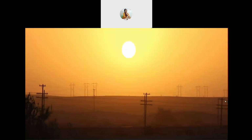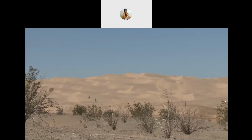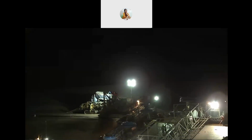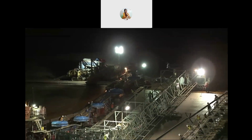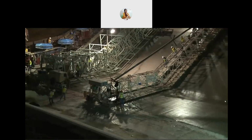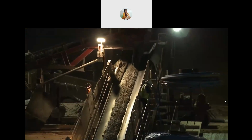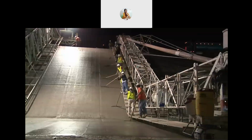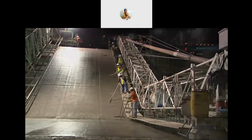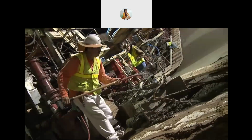Both man and machine were challenged by the same desert conditions: heat, wind, sand. During the summer months, temperatures regularly hit triple digits. Construction work schedules were shifted to night when temperatures cooled. Chiller tanks provided cooled water for mixing concrete. It was necessary to place the lining in the relative cool of the night, when temperatures came down into the reasonable mid-80 degrees Fahrenheit.